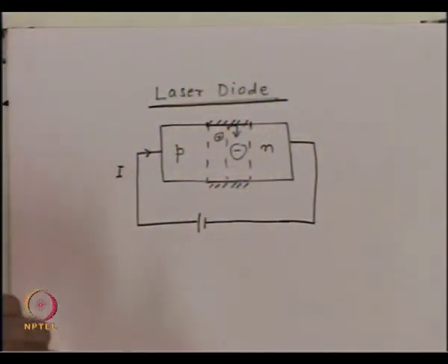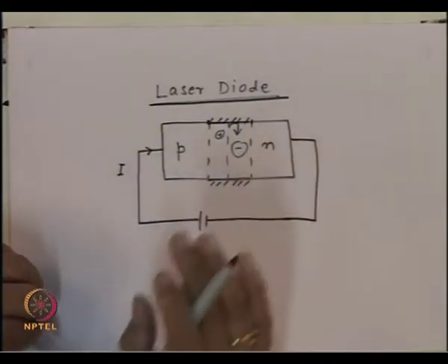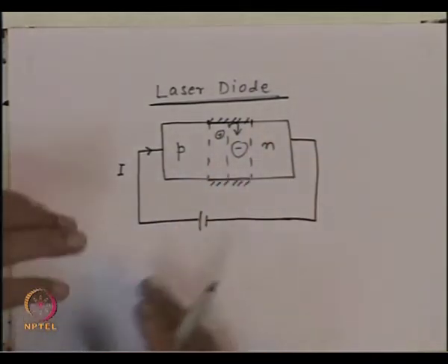So, you will see essentially what we are talking about here is that once the electron hole pairs are injected inside the region, then as long as the electron hole pairs remain inside this region, we will not be able to change the light output even if we switch off the current externally. And the lifetime which we have here is essentially decided by the stimulated lifetime of the carriers.